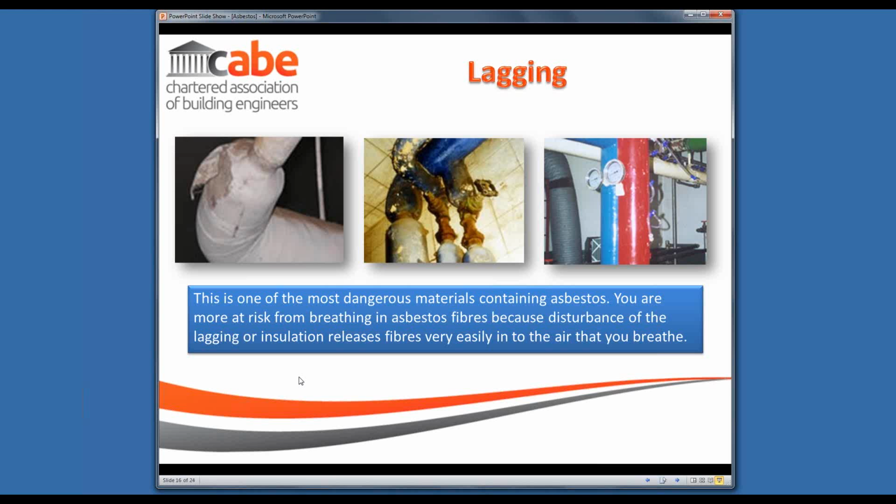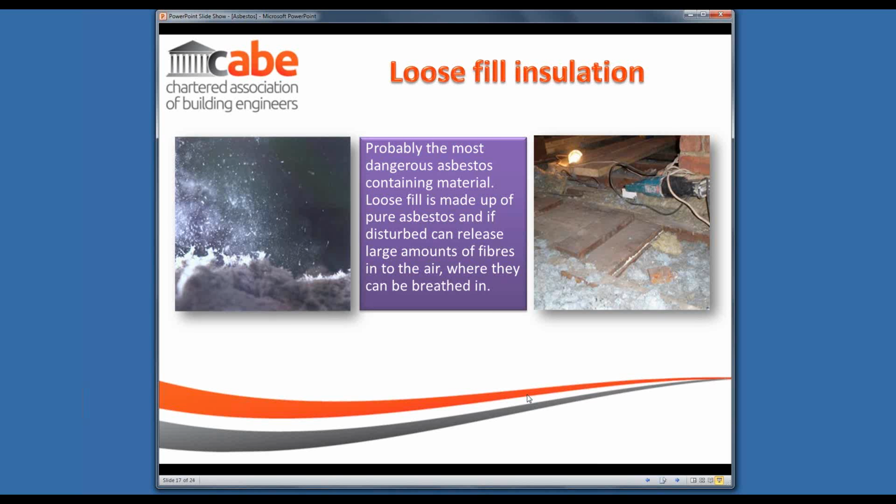And then questions in terms of if somebody's taken down an Artex ceiling which may or may not have had asbestos, what should be the advice there in terms of cleanup? So if somebody's already removed asbestos, really the advice in terms of cleaning, if the product's already been removed, is that there is a thorough clean so that there's no possible particles left lying around anywhere.